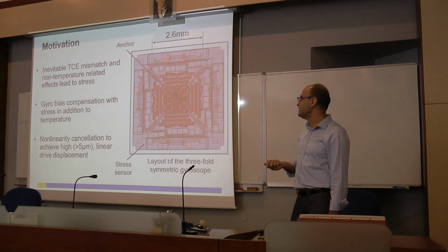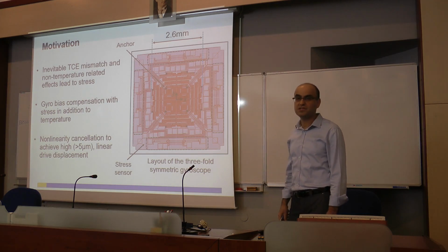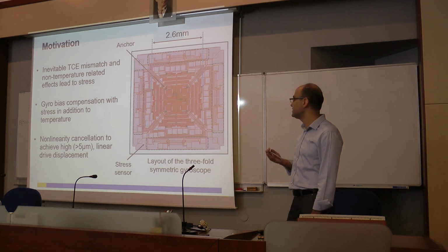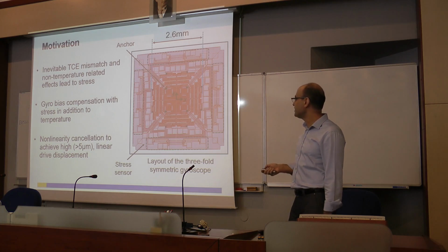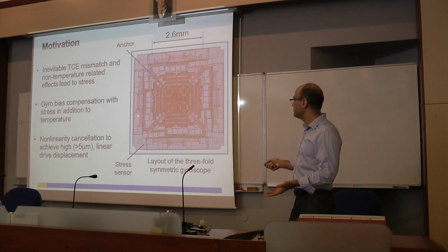As I said, the goal is doing stress compensation, and for that reason I put the gyro in the middle, and I have stress sensors surrounding the gyro. This stress compensation has to be on chip, because the stress is very position dependent. If you put it somewhere else, it is very likely that your device and your stress sensor will see a different stress. The stress sensors are on the side.